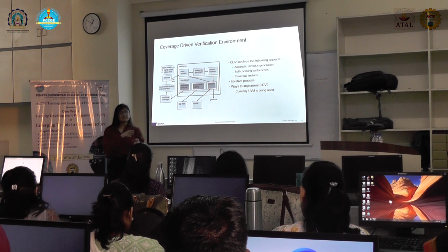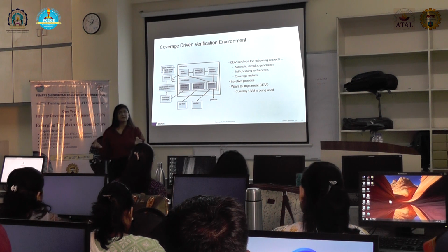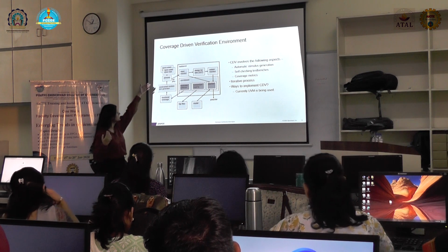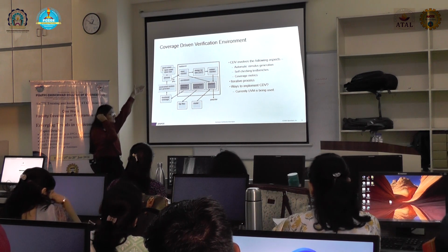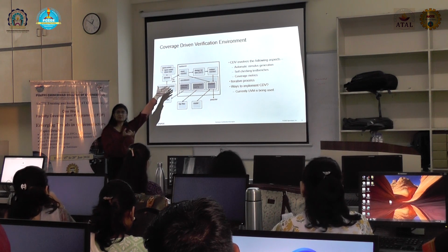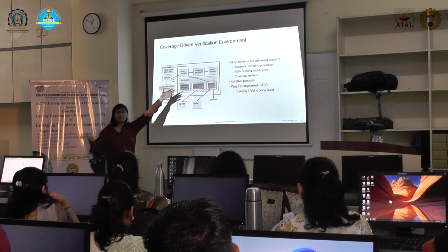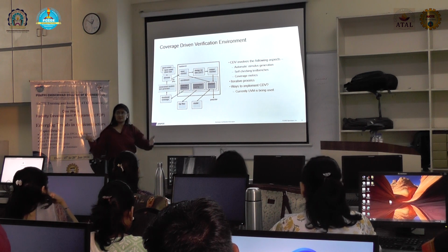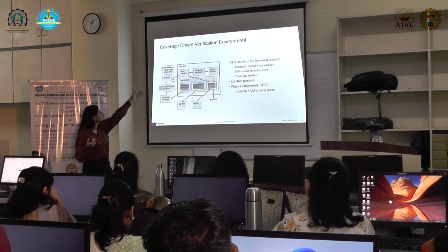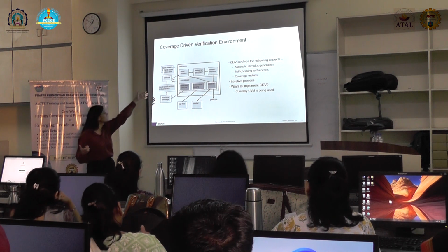So for those specific scenarios, what we need to do is create a directed test case and cover that in our coverage. A directed test is nothing but manipulating the constraints. We check the stimulus and create the stimulus according to the missing part that we did not cover in the regression, and we run that particular test. So that is one of the major changes from Verilog to SystemVerilog.